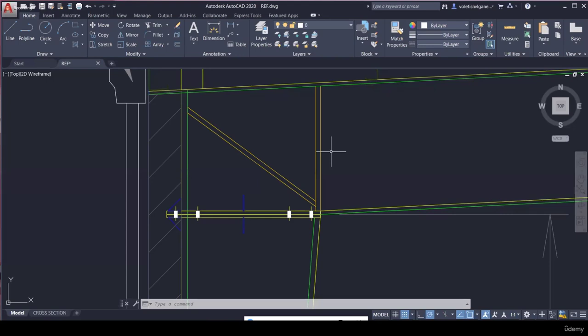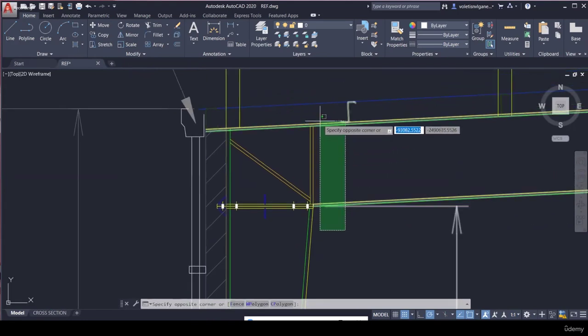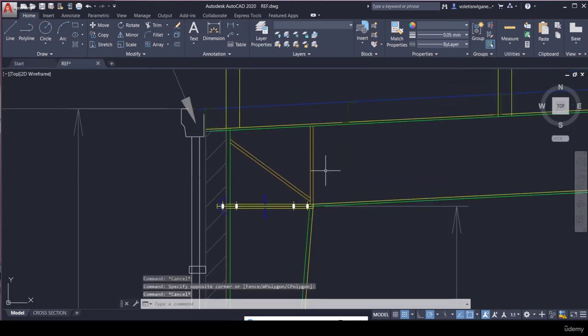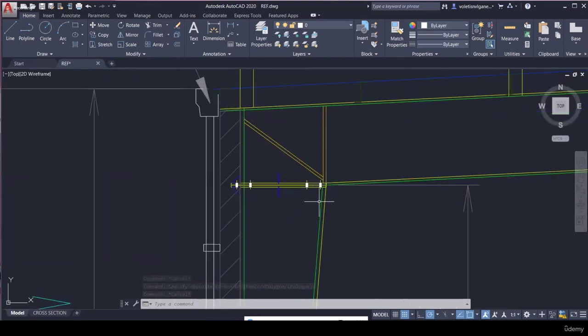No, actually, the size of the end plates is based on the depth of the rafter at the haunch portion. Whatever depth is provided at the haunch portion, we can use somewhat higher than that, which has to satisfy the connection requirements.